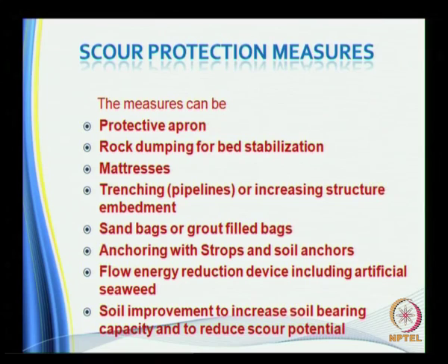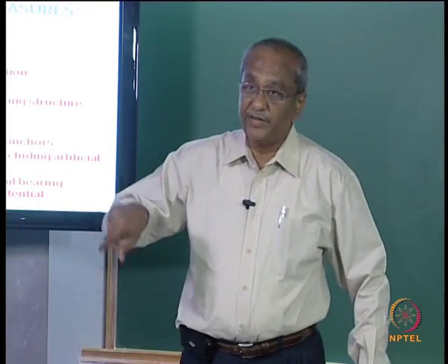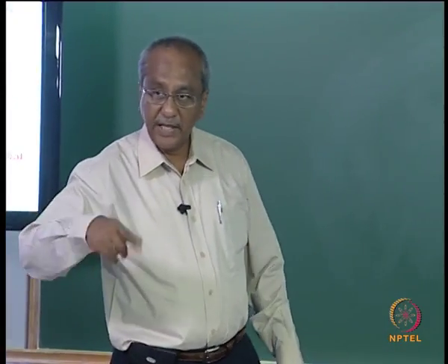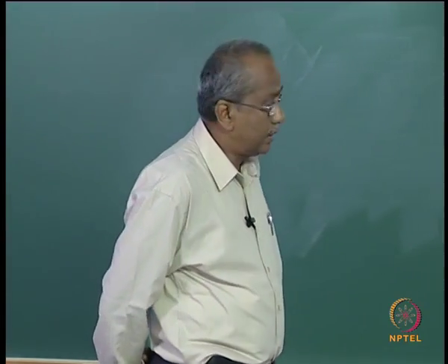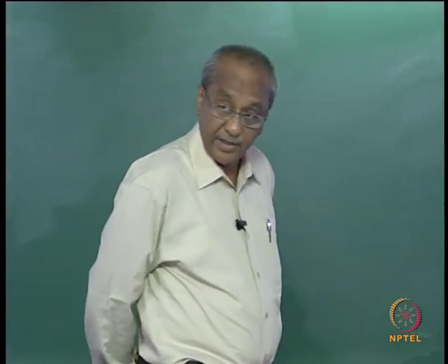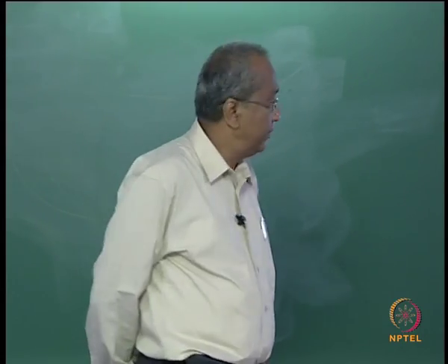Then trenching. This particularly is very important in the case of pipelines, and I would say even in the case of breakwaters, if you have an excavated toe, you need to have a kind of trench wherein you can place your toe. Although difficult, it is extremely effective.